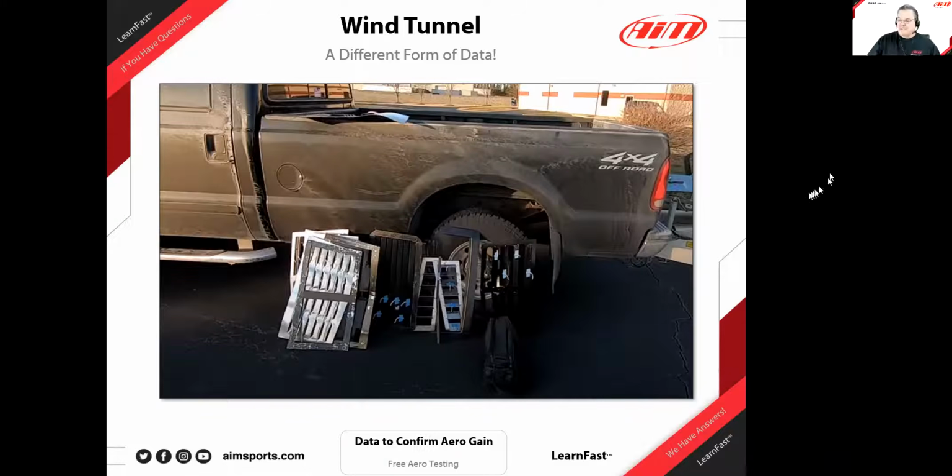Yep. And some of this is available to racers that are going out on the track. I see it in Formula One, I see it in IndyCar, maybe even some stock car guys back when they tested a little bit. They would get what looked like a good thick oil, but it was fluorescent yellow or fluorescent orange, and they would put drops of that on the leading edges, and then go out and run, and the wind slowly drags that back, and they can come back and look at it. Virtually the same thing we're getting here, and all of us have that available to us if there's a concern about a certain area of your car. Right? Yeah, you can always do a poor man's flow viz, little oil drops, and just see which way they go around a certain thing.